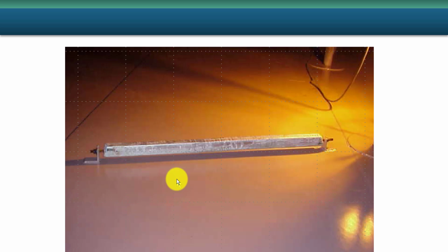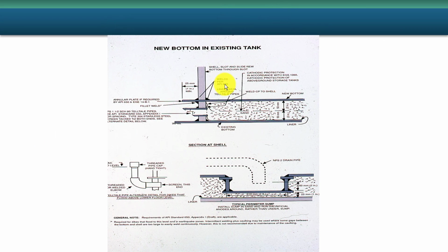But no coating is perfect, and so by adding the sacrificial zinc anode, what you're doing is protecting the coating from failing because of small discontinuities and holes and defects in the coating system. And so the current requirements aren't very high, and this anode can last 20 years. If you had no coating in here, you'd have to space these every couple of feet and they wouldn't last a year. Here's a schematic of a double bottom.